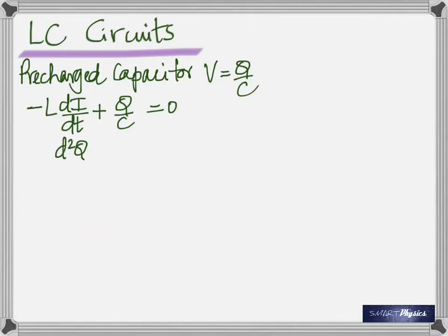The capacitor had energy, right? Now it's gone, completely gone. It's discharged. What happened to that energy now? All of it became magnetic energy across the inductance. And remember, there are no dissipating forces in the circuit, no resistance. So energy is not going to be lost at all. So what's going to happen?